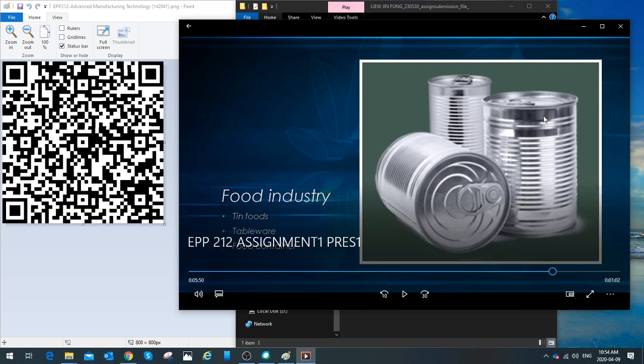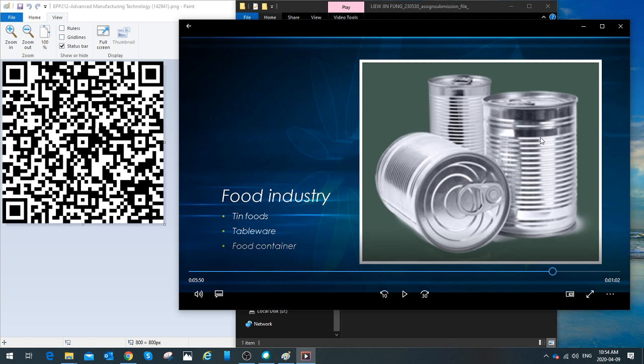These tins, the reason they call it tin is that they are being electroplated by tin, or they have been dip coated, dip melted, coated by tin. It means that the steel sheet has gone through a hot bath of molten tin, and then it is coated from both sides or from one side. It depends on the process, but that one is not electroplating. So we have to be careful when we are talking about a process.